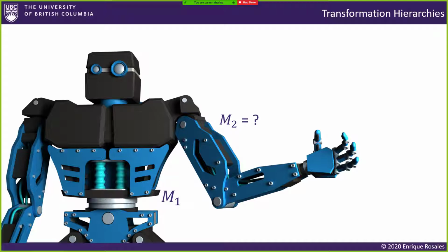Pavel says, nice, it saves a lot of going back to origin and coming back. Exactly. That is basically what we have here. It's way more convenient. Okay, so M2 will be some matrix, and by some matrix, I mean its local transformation with respect to its parent. Because this piece could be rotating. In this case, obviously the pieces of the robot are attached, so they cannot move per se, so it's only rotations. So this some matrix is its local rotation times the matrix from its parent.